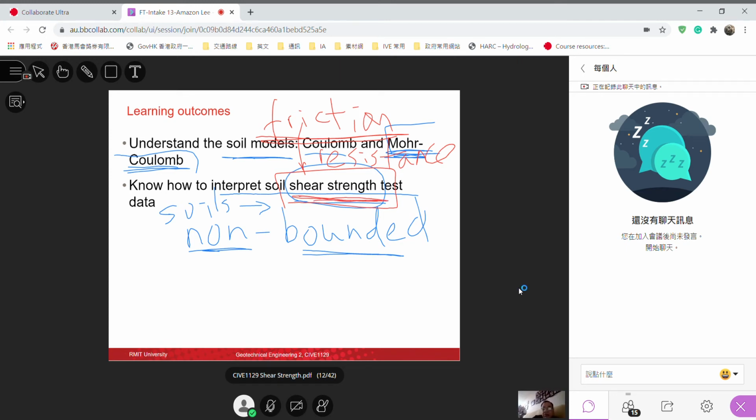Okay, so it's not bonded. It's not concrete, where you have cement paste bonding everything together. Even though there's no confining pressure, you have a whole block of cement standing alone, a whole chunk of structural steel standing alone, no problem. Still very, very strong. But with sand, if you don't have confining pressure on the outside, basically it's just a pile of loose sand, a pile of loose particles. It's very, very weak.